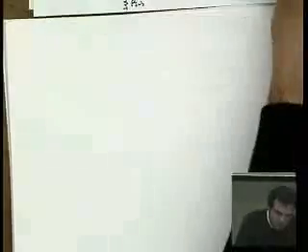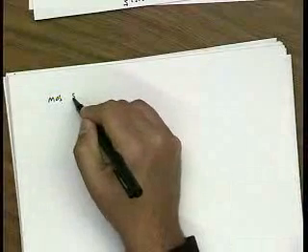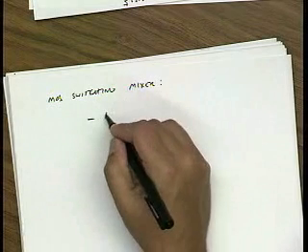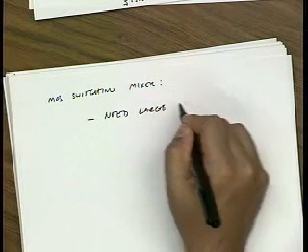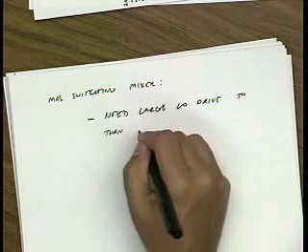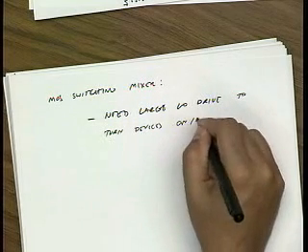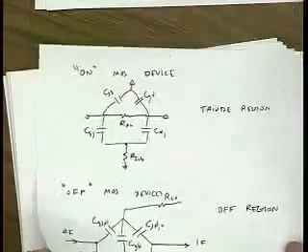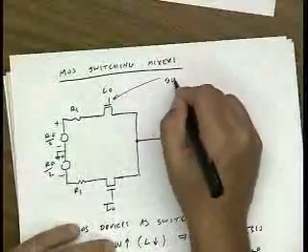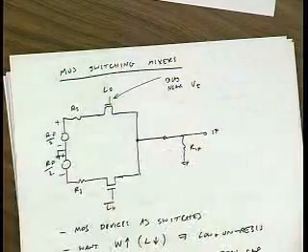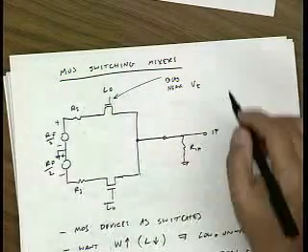So one of the issues with a MOS switching mixer is you need a very large LO drive to turn the devices on and off. Okay? You also need to bias these appropriately. For instance, a good bias point might be to bias these devices near threshold, so that any positive LO turns it on, any negative LO cuts it off. So I haven't drawn the DC biasing here.